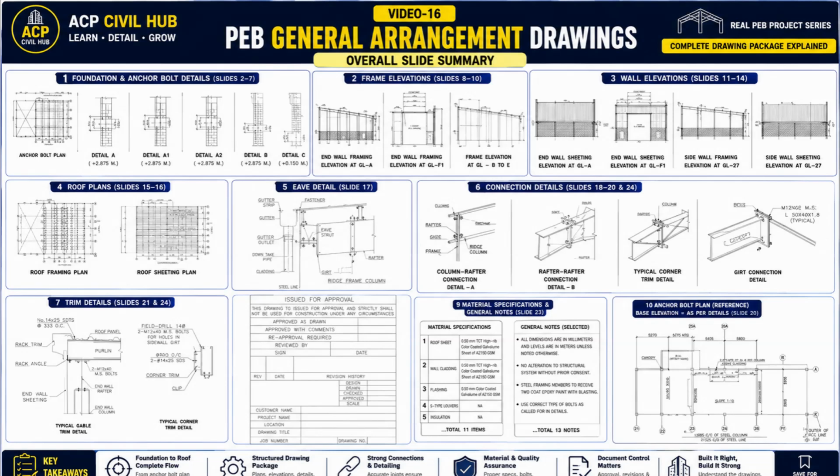We also studied important connection and trim details, such as column-to-rafter and rafter connections, girt connections, flange braces, and typical eave, corner, and gable trim details. Finally, we reviewed the material specifications, general notes, bolt and fastener requirements, and drawing approval information that must be carefully checked before fabrication and construction.